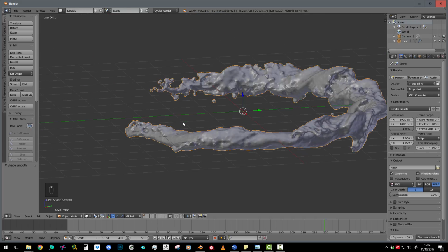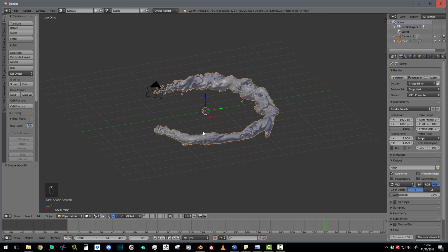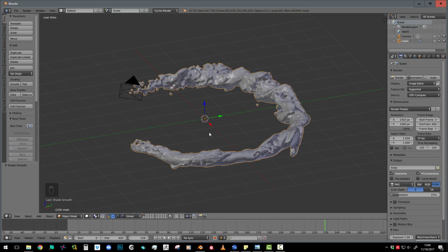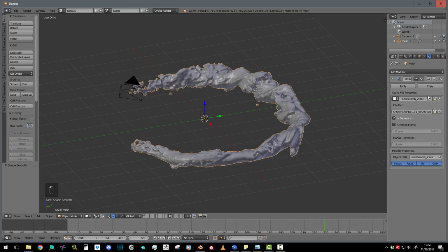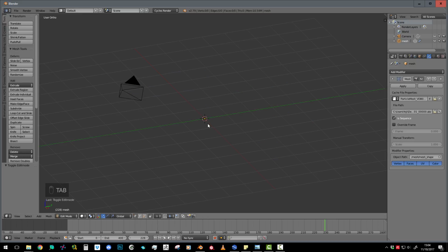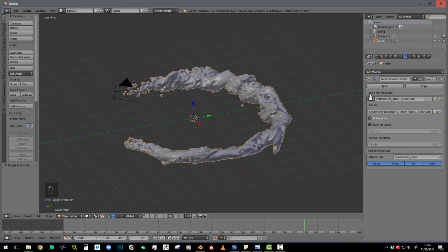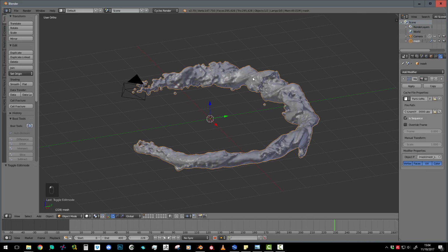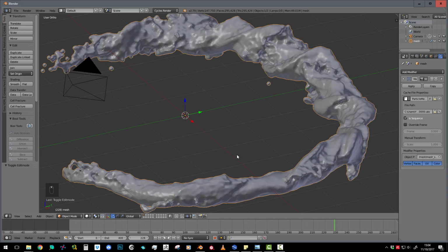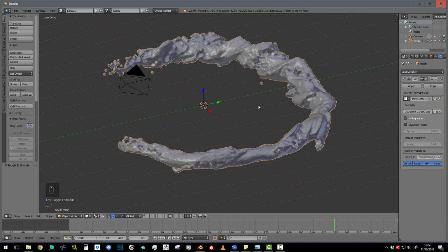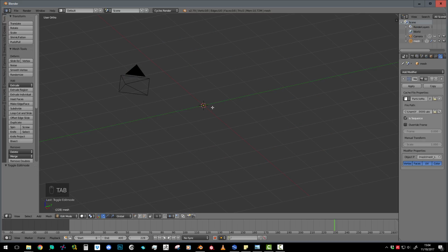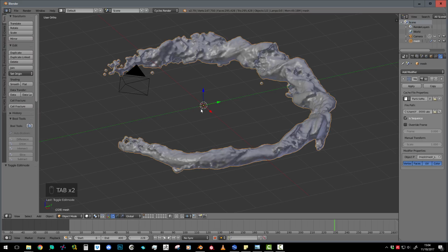So it took me a while. I did some research, and actually it's pretty simple. It's because here it's an empty mesh. When you go into edit mode here with Tab, you can see that it's an empty mesh, but it's this modifier, a mesh sequence, that the Import Alembic does, that makes this mesh. So Blender cannot understand that a mesh with no faces can have smoothing on faces, so it does nothing.